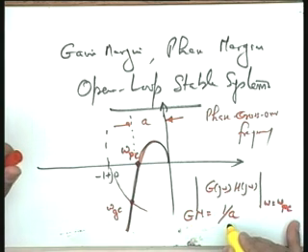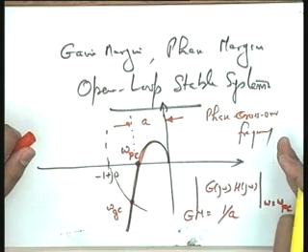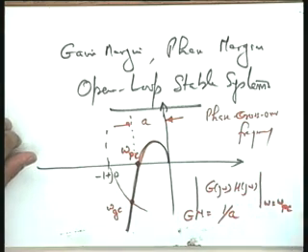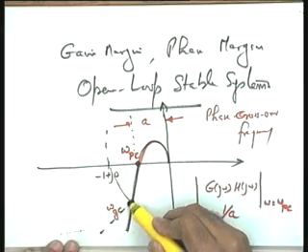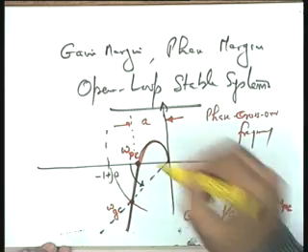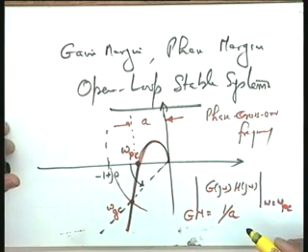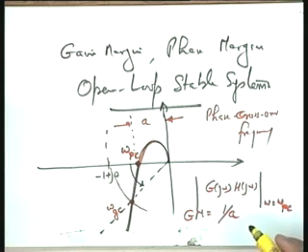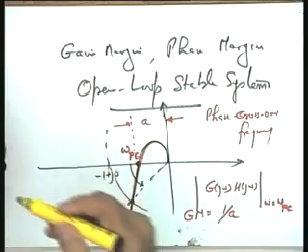Otherwise, it represents the factor by which the original gain of the system can be changed. Okay. So, lastly let me explain the phase margin, and here I will draw a line. I will measure this angle, and this angle I will call the phase margin. This is the margin by which the phase can be increased, and now you can see that.